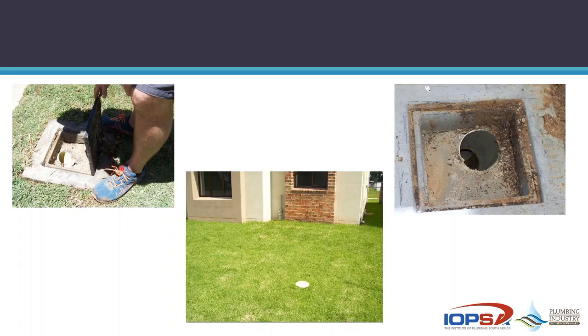And then when it comes to the bolting down, you'll see these are all little single seal covers. These should have had bolted airtight covers. You could still have that if you had the normal cover in there, but you can see this thing, even with the paving and the grouting, is already sand going in there. Same over here. You've got a nice cover there so you can actually find it, but there's smell coming out of the single seal cover. It's not watertight. So if there's any pressure on this, if you plunge further down or further up the line, then you'll probably find that this lid starts jumping up and down with the pressure being applied from the water.